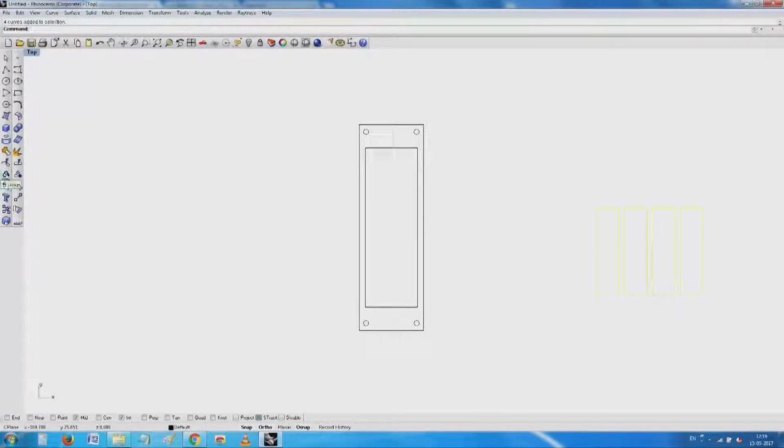So we are already on our way. Two of the things which I have created, including the display, and then I have the power supply. Maybe I will group the whole lot and lock them together. Now if I move one, the other moves absolutely. Now it is for me to decide where to put the PCB, where to make an outline, how much space we have here.